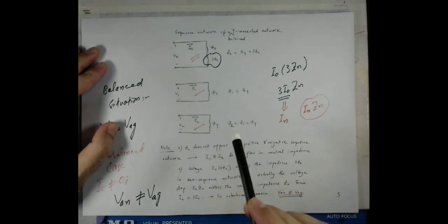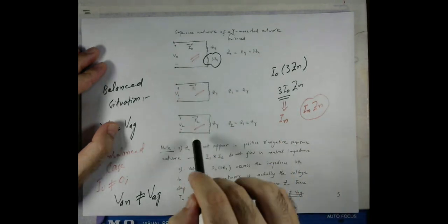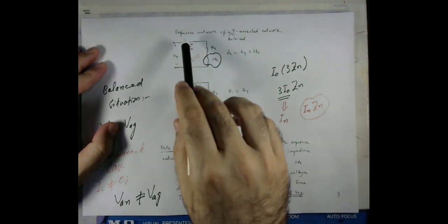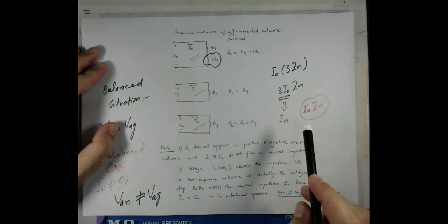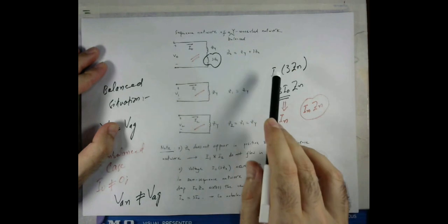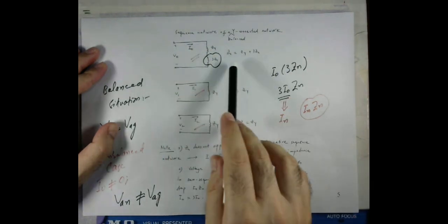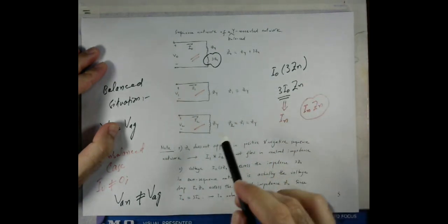Also we observed that the positive and negative sequence currents only flow in their own networks, but these currents do not flow through the impedance that we called Zn. So through Zn only the zero sequence current flows. And we also made this observation that the product of 3I0 Zn, or basically in the network, because to the zero sequence current 3Zn is offered, but actually 3I0 is the neutral current.